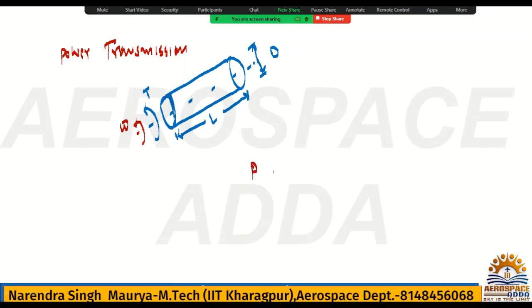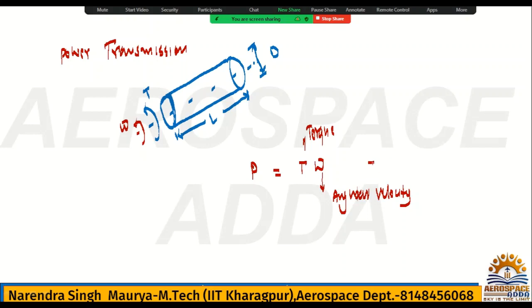Power is nothing but the torque you have applied to the shaft into angular velocity. Now you know very well that T, and what is the angular velocity? It is 2 pi n. So P is equal to 2 pi nT. This formula you have seen many times.